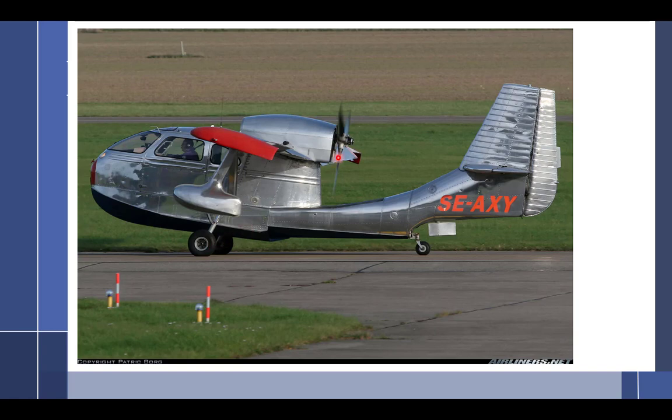So, all right, prop is mounted on the rear. More susceptible to damage from rocks being kicked up by the main landing gear or spray being pushed back there. So it's a little more susceptible. That's why you're going to find them usually mounted higher up. Even if you think about our Skymaster outside, the front prop is much lower than the rear. The rear they put up quite a bit higher.